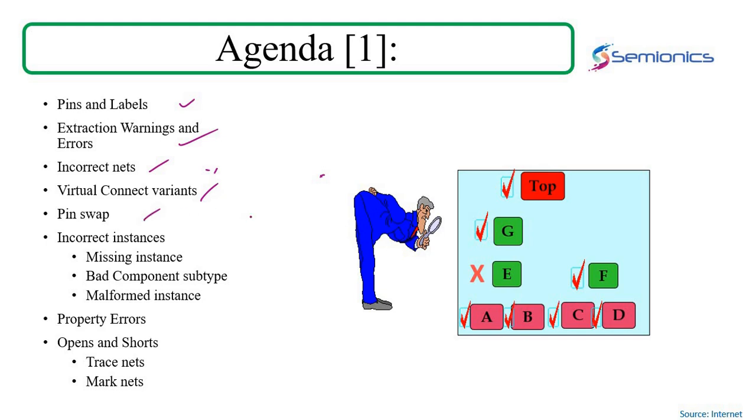Then we would have come across scenarios where sometimes you would have ended up swapping the pins. It becomes slightly tricky to debug the error, but still the error shows up. So are there any settings in the tool which you can set to get rid of these errors? It will be easy for you to pass through this pin swap related LVS error. We look into that also.